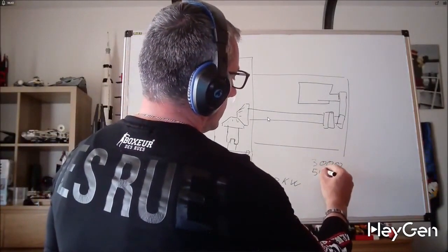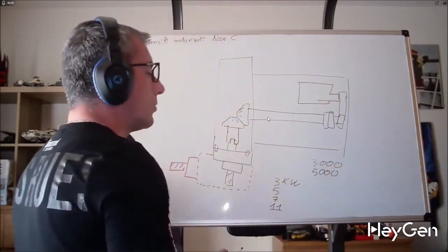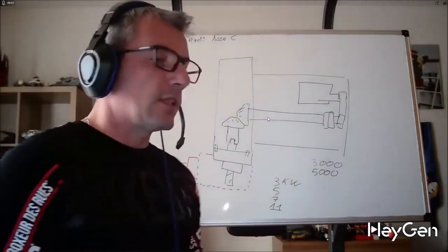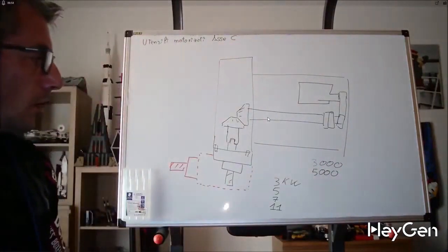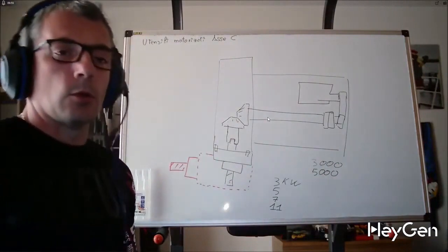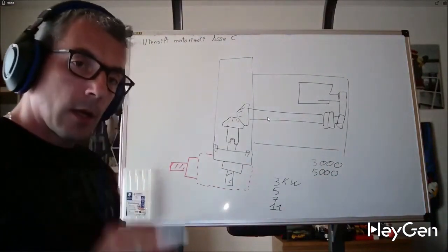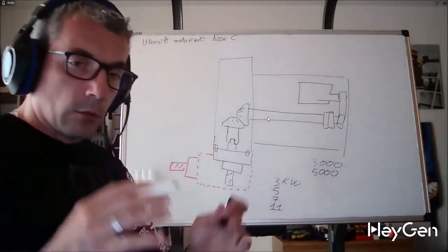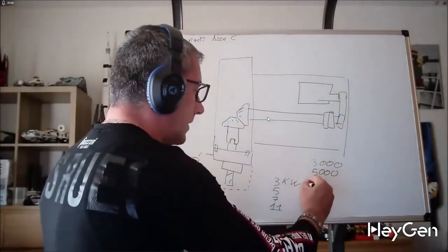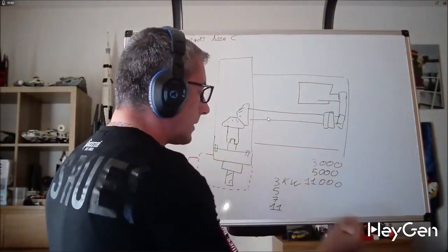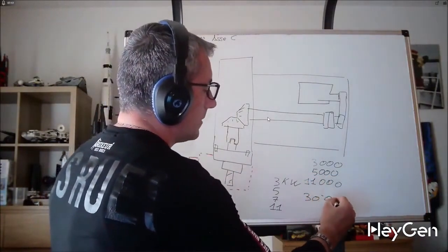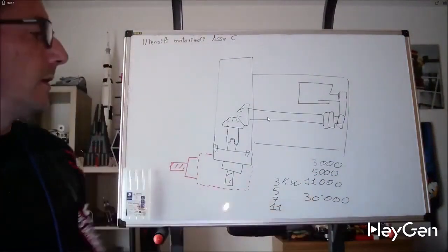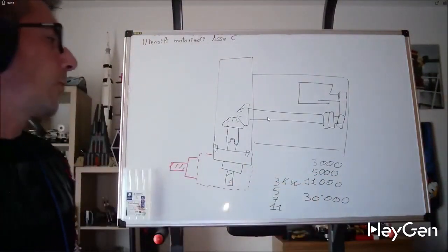The first powered tools had 3000 RPM, and today I've found some Doosans that do 5000 RPM. I didn't have that. I had a Puma 3100, which did 5000 RPM. I don't know if we've improved in this area as well. They are making giant strides. But I remember that when I was buying my Doosan, I went to see CMZ, and correct me if I'm wrong, but it reached 11,000 RPM. A machining center has 30,000 RPM, with power and torque to spare. Here we don't have power and torque to spare.